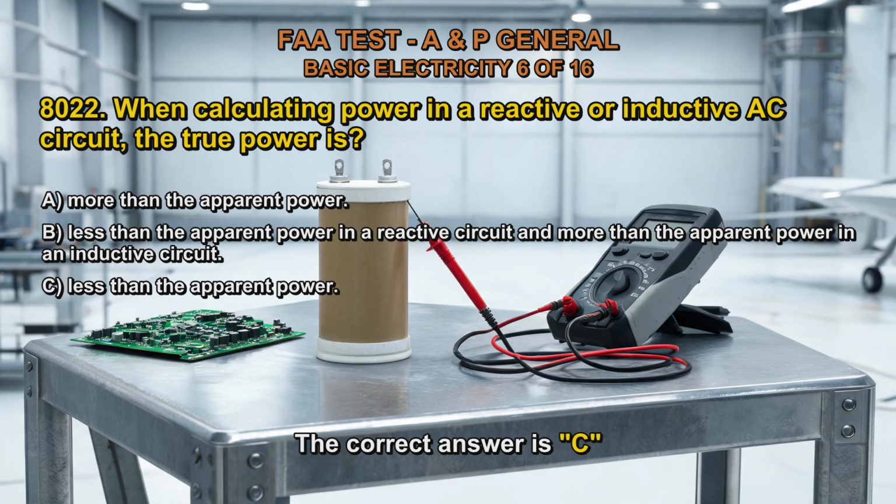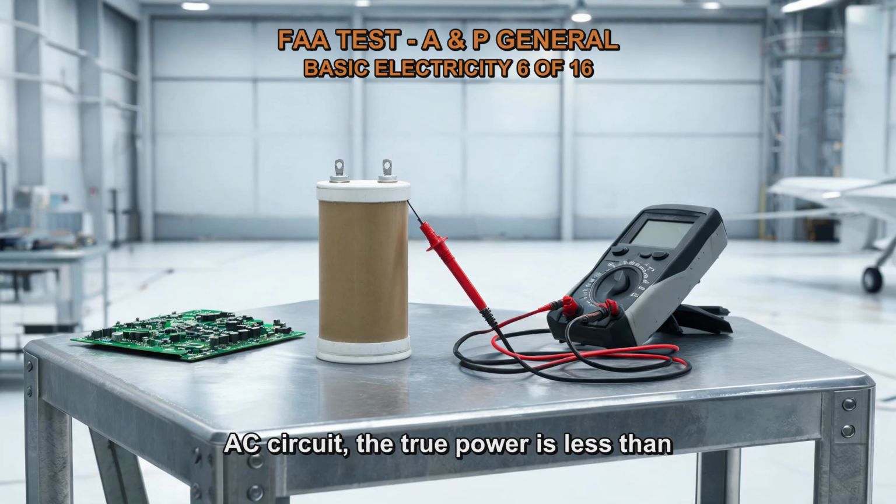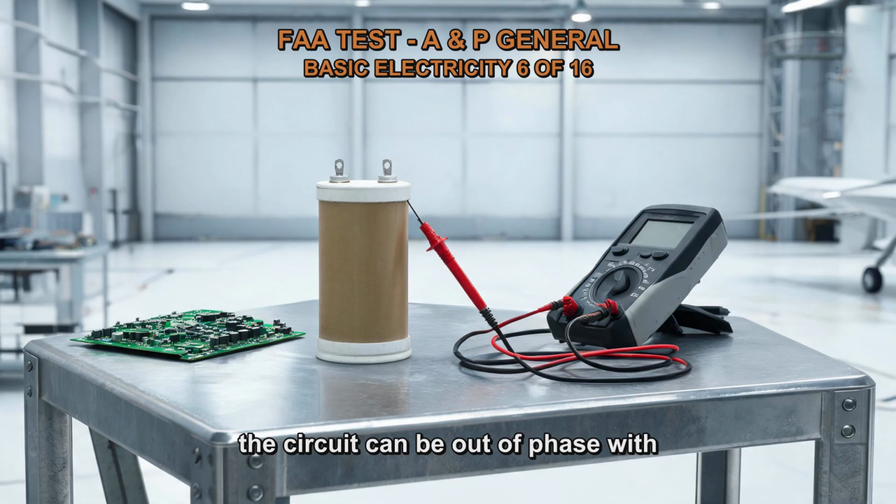The correct answer is C. When calculating power in a reactive or inductive AC circuit, the true power is less than the apparent power. In an AC circuit with reactive components, such as capacitors or inductors, the current flowing through the circuit can be out of phase with the voltage. This means that although there may be a current flowing through the circuit, it may not be doing any useful work, such as lighting a light bulb or running a motor, because the current is not aligned with the voltage.